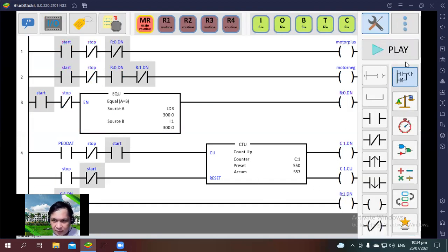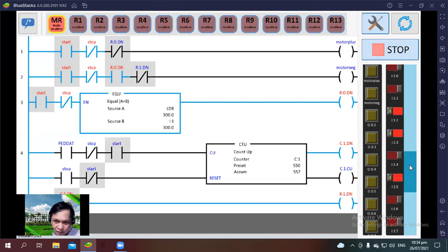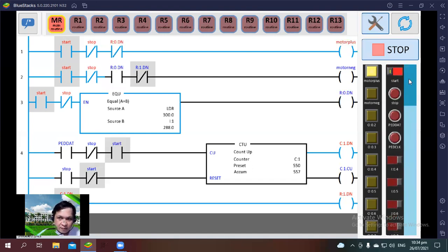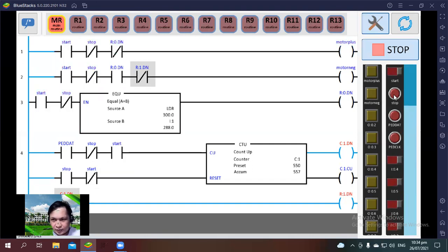Okay. Again, when you turn it on, it won't turn off because this one is still at 300. You have to change a value on it. Then, to reset the function, start, stop. Only then will it reset. It's a lot easier for actions like a pulse with a push button.